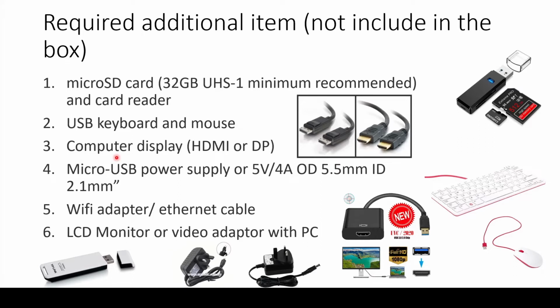But if you are doing some heavy processing that requires a fan to cool off your Jetson Nano, and the power supply is not enough, the Jetson Nano will automatically shut down by itself. It won't continue the process, to prevent harming the device.